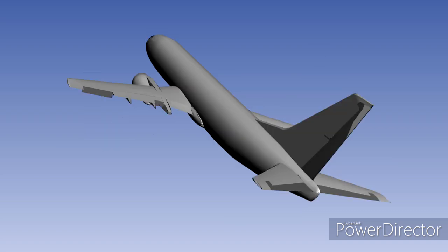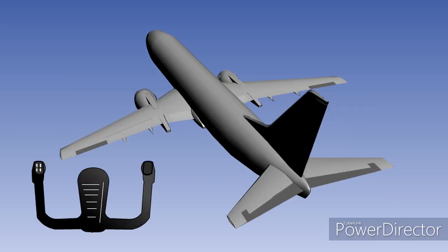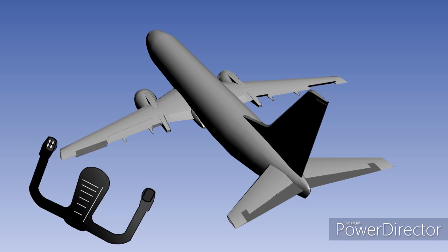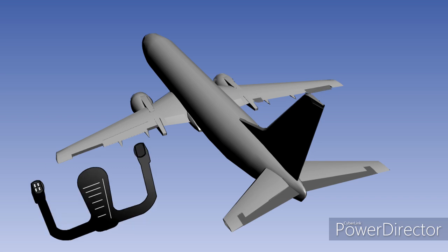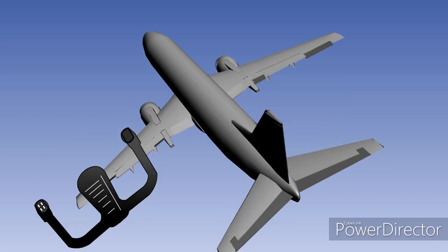The lift forces are now out of balance, and the aircraft will roll to the right. It will continue rolling to the right until the ailerons are returned to the neutral position by the pilot. Movement of the control column or yoke is instinctive. If the pilot wishes the aircraft to roll right, the yoke is rotated right. Rotate the control to the left, and the aircraft will roll left.